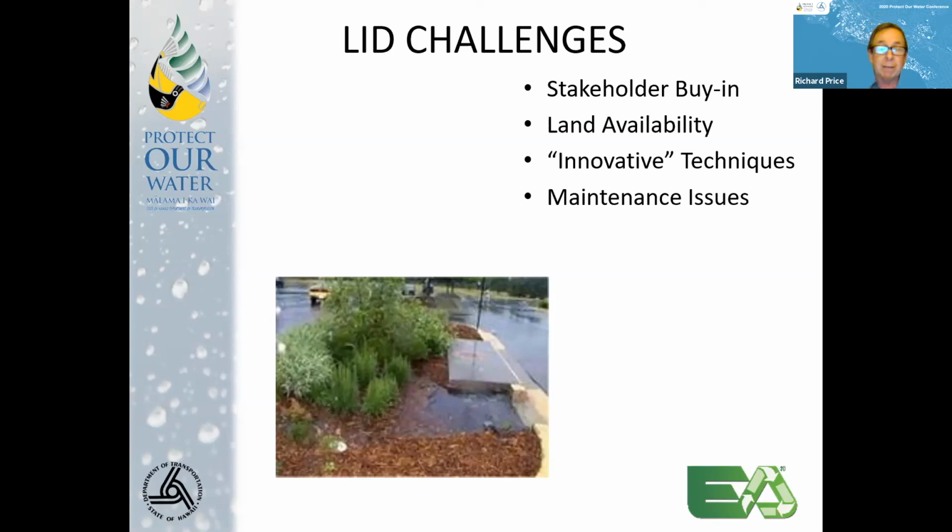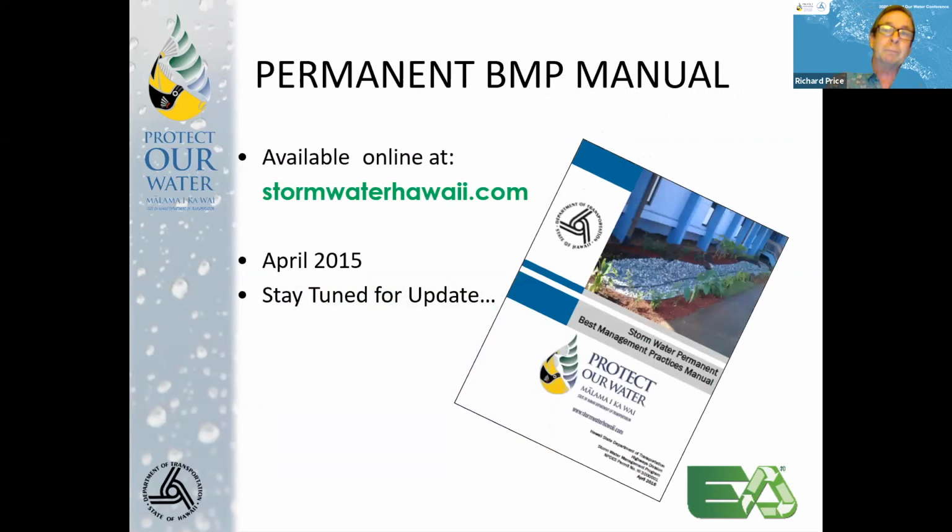It's an innovative technique, and this applies all the way down the line, from the design to the construction to the training of your construction inspectors, because when the contractor delivers a bioretention soil mix, have they seen one before? Do they know how to review it and see if it meets the spec? And is it the right thing? And then, like I mentioned, maintenance issues. If it's going to capture trash, we've got to clean it out.